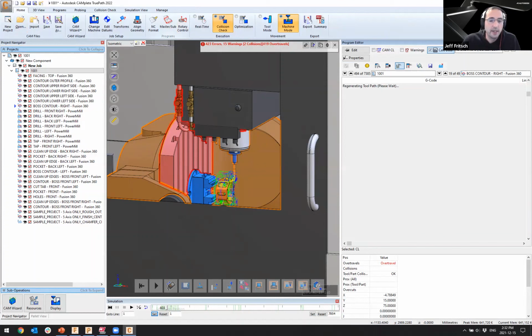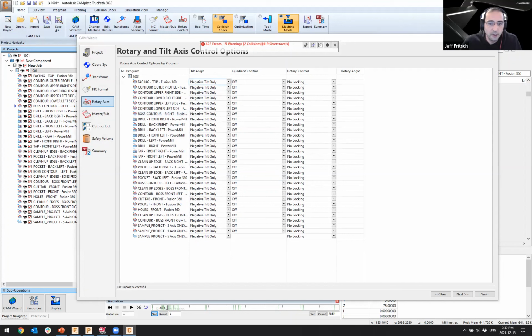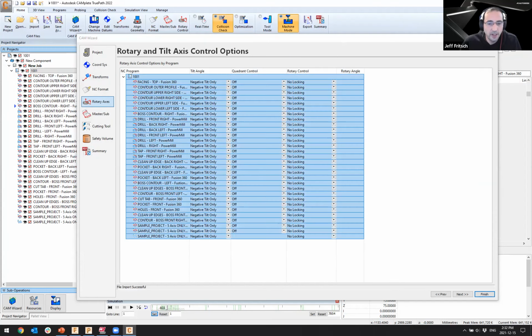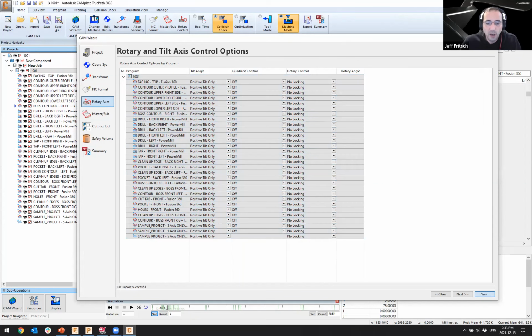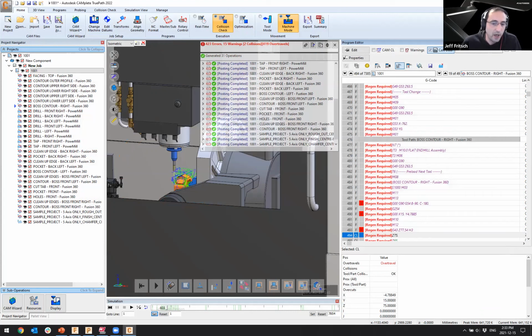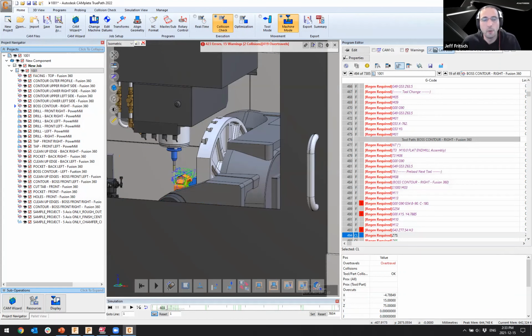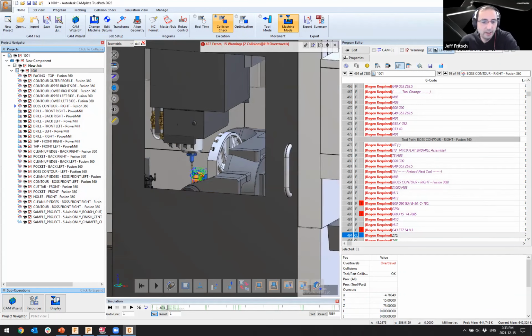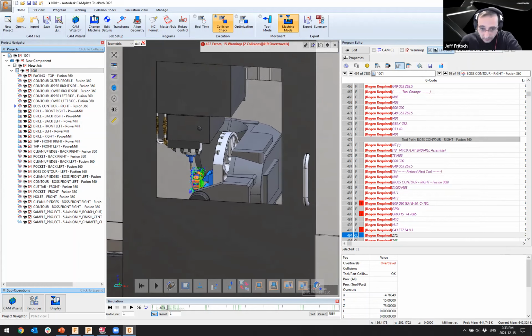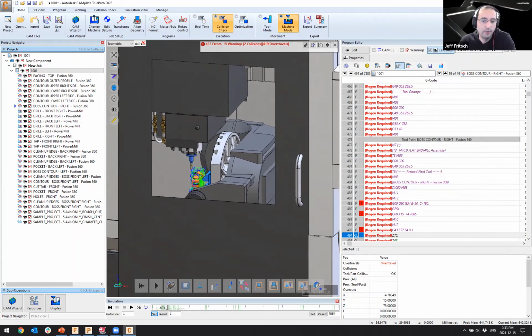We want to make sure that now these ones are going to be fitted within what the machine is capable of doing. So I'm just going to be looking at which side of the trunnion I'm tilting on, and instead of working on the negative side, I'm just going to be working on the positive side and now have an appropriate solution. So at that point, really the issue was more so driven by how the machine would react to the code.